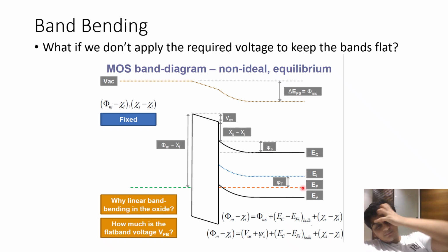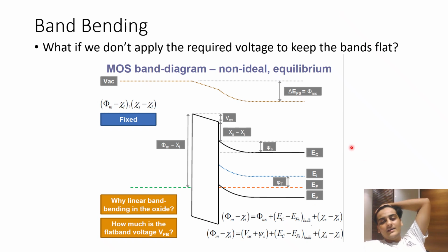So now at this point where you're very far away, you're behaving like a pure semiconductor. So your difference with the vacuum level is going to be precisely the work function. This difference between EF and the vacuum is going to be the work function. And over here, the difference between EF and the vacuum is again the work function of the metal.